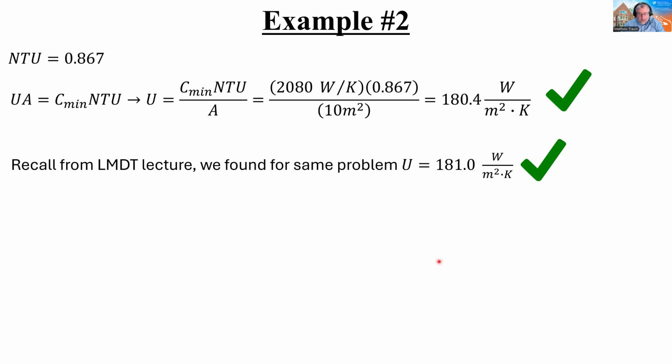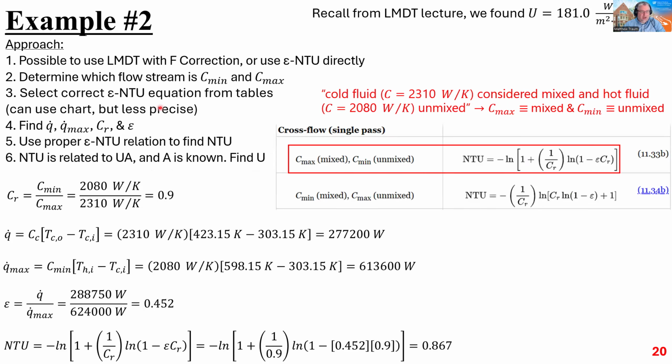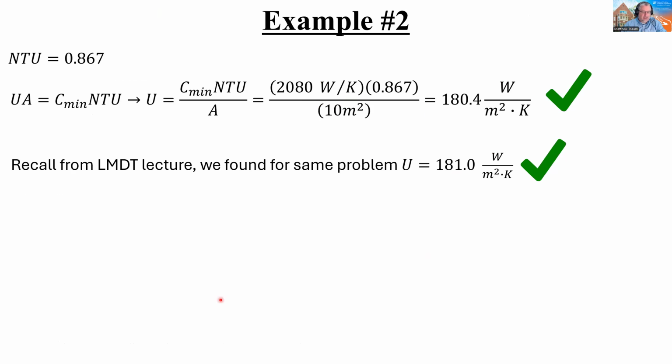Hopefully it was helpful to see going through that technique both ways. When we did it with LMTD, we had to find all kinds of correction factors, and it was a god-awful mess. With Effectiveness-NTU, it's super fast. I did it in one slide. That gives you a sense that both approaches are correct; sometimes one approach is more efficient than the other.